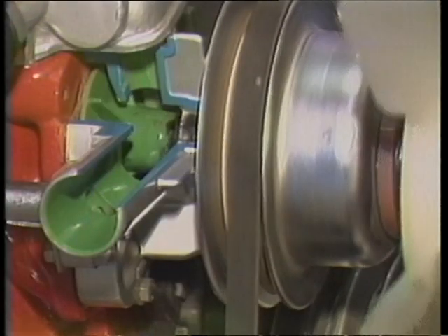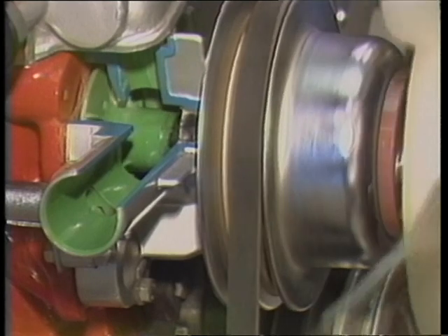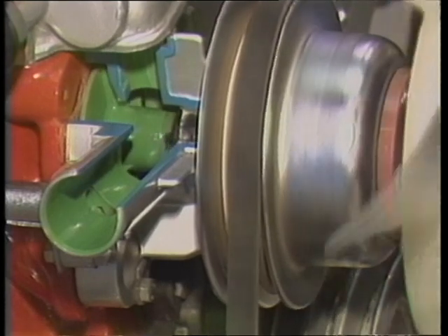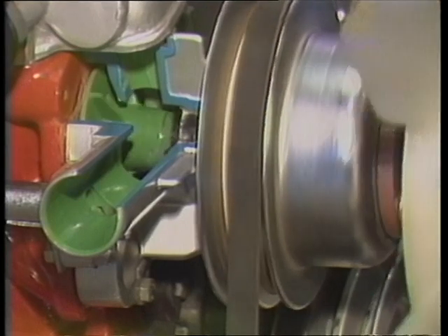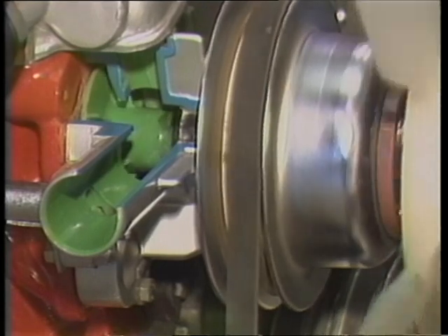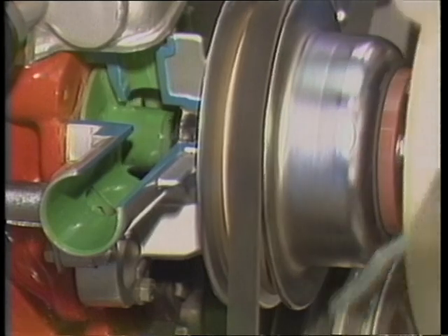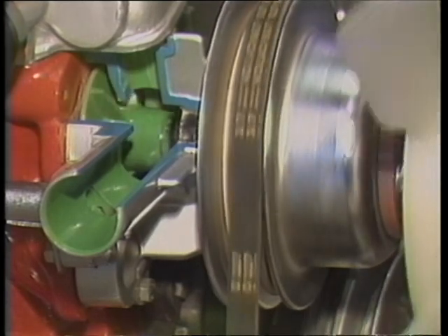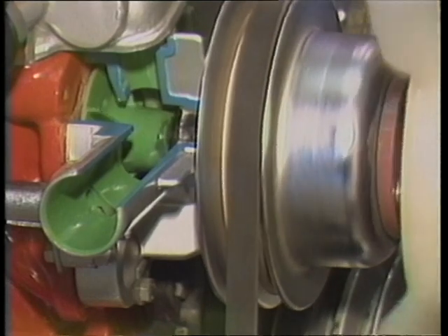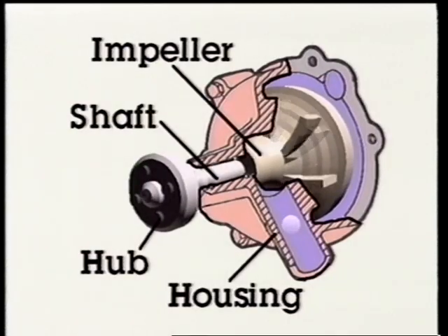This cutaway shows the basic action inside a water pump. The engine belt turns a water pump pulley. The pulley then sends power into the pump. The spinning impeller can then pressurize the coolant, forcing it through the engine under pressure. The impeller uses centrifugal force to form pressure.